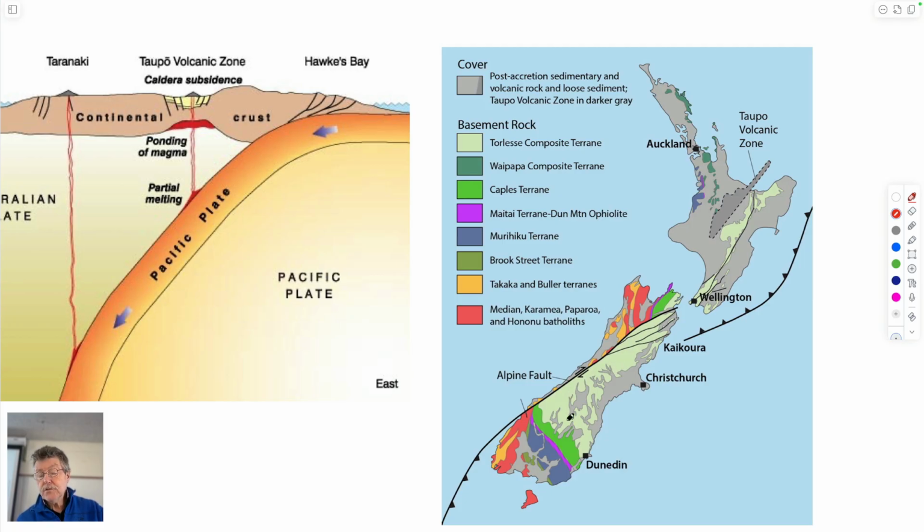Lots more hydroelectric power schemes in the Southern Island just because of the topography. So I guess we know that on the South Island, we know that rho g h Q. So not heat rate, but power from hydroelectric dams is proportional to the volumetric flow rate, the density of the fluid, water, and the elevation drop. And so where you have high elevation and a large volume of fluid, because you have decent sized catchments but also large rainfall, makes it ideal for hydroelectric.